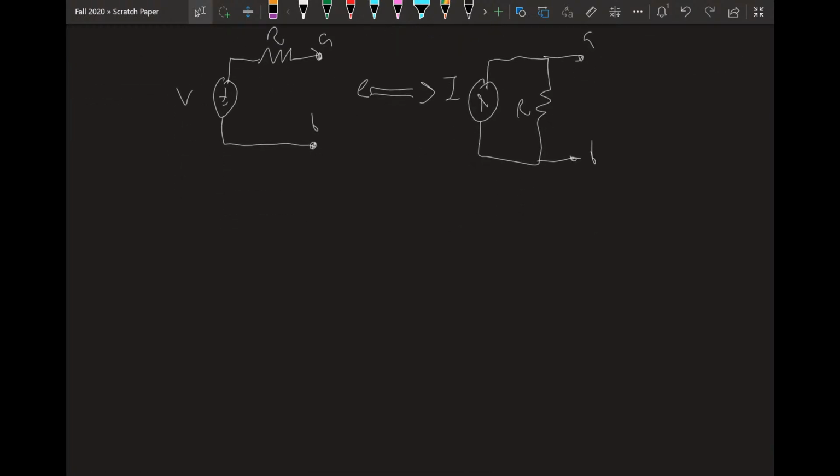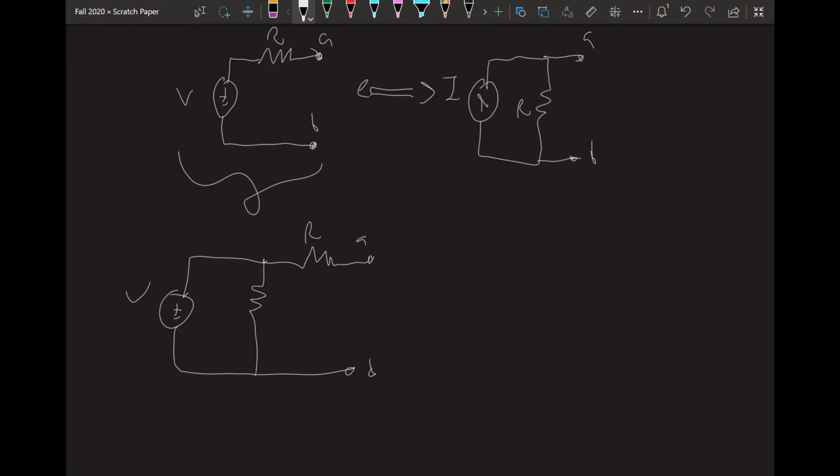So a couple things to note here. One, looking at the left configuration, if we put a resistor in parallel between the voltage source and the resistor, like this, across those same terminals A and B, and I'm going to call this blue R, it does absolutely nothing to affect whatever is between A and B. Because we'll notice that the voltage appearing here is still V. So nothing has changed, which means this can be reduced to just this again.